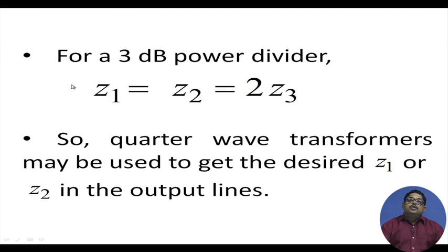We will show you that a 3:5 or some ratio we will take, and there we will show that by choosing proper impedances you can design. Now, characteristic impedance of the lines or of the waveguides etc., they depend on their dimensions. So for a coax line you will have to choose the b by a ratio correctly, so that you get some impedance.